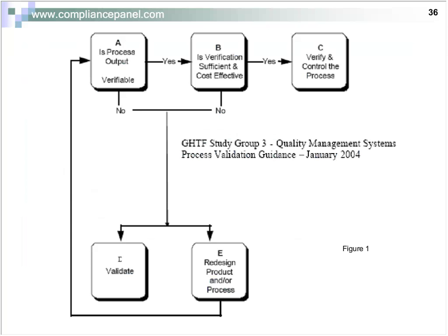We can validate the process, or we can redesign the product and/or the process so that we can get back into verification. So that is always an option for us, to redesign the product or the process to get around having to validate a process. Of course, this is expensive to do in most cases, late in the design process, to go back and redesign. So this step isn't often taken.